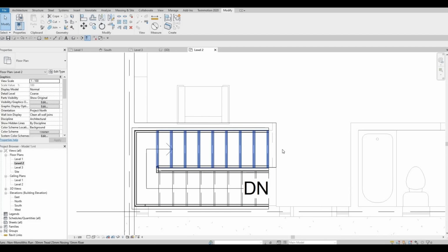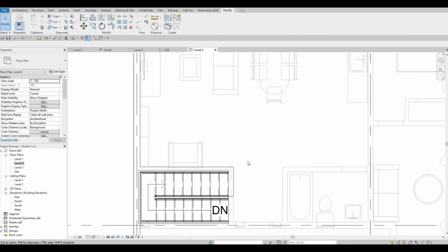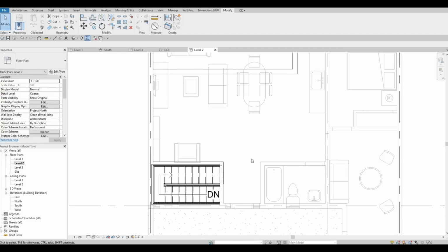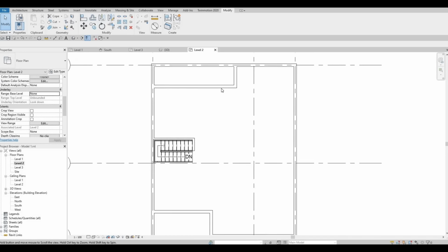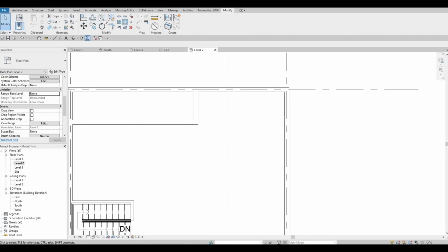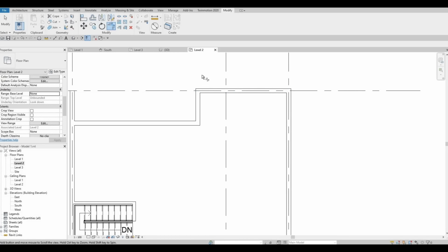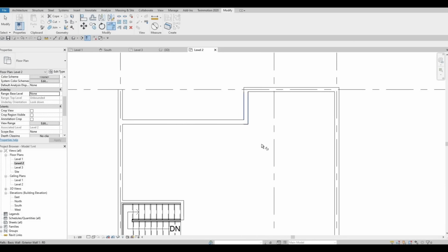So now we could go down. This is covered because we could actually add in a railing, but wall is good for now. So now that's done, we can actually change the underlay. So go to underlay and then base level range should be none, and then apply. And then we're also going to trim this part. So TR, and then now it's open.